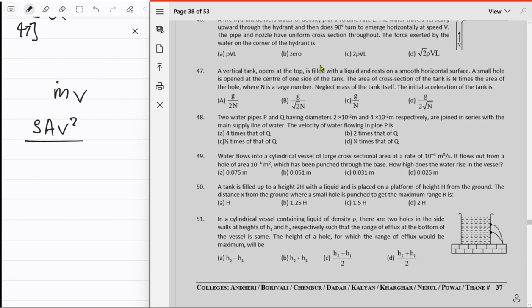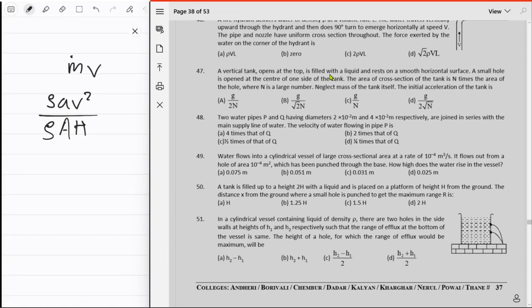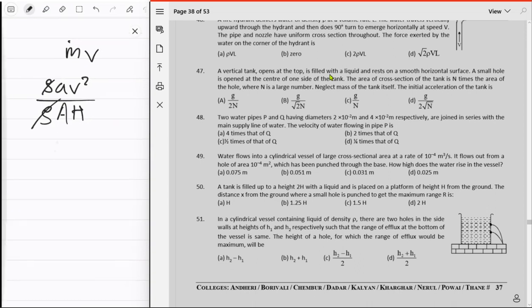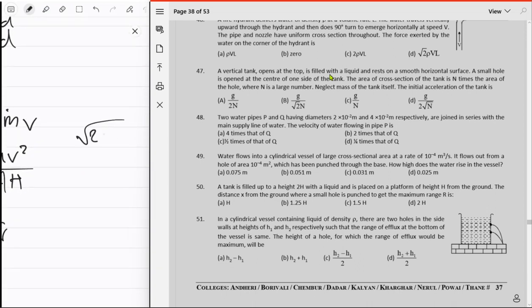So just the density of, oh, we should actually say small a, upon capital A times the height of the thing. And where is this though? Well, we don't know that, but whatever. Okay, and a upon A cancels. A upon A is just 1 upon n, and then you've got v squared upon h. But v squared is just 2g small h.